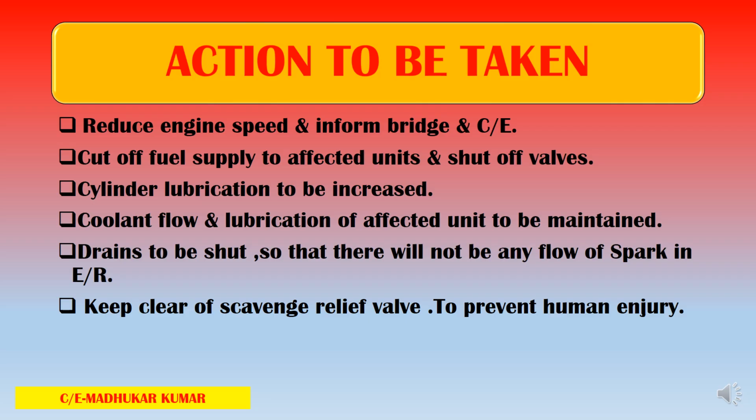Cylinder lubrication of that particular unit has to be increased. Coolant flow and lubrication of the affected unit to be maintained. So this is a very important part. Drains to be shut so that there will not be any flow of sparks in the engine room.